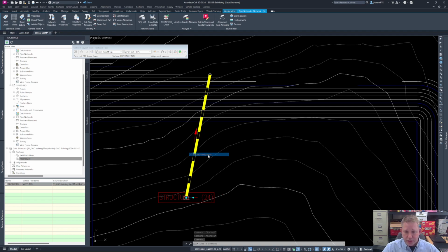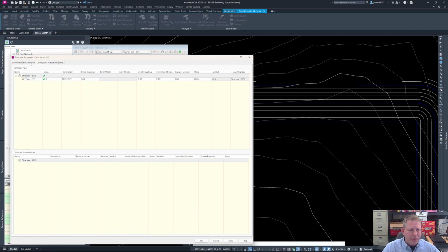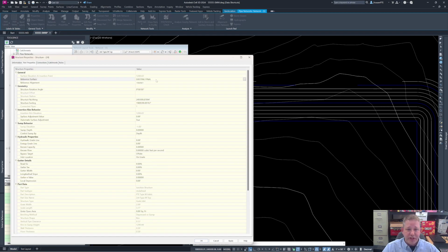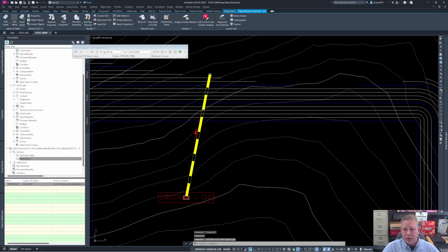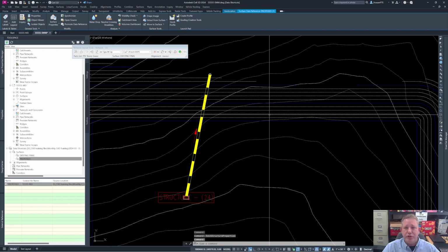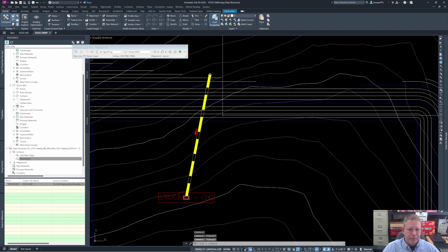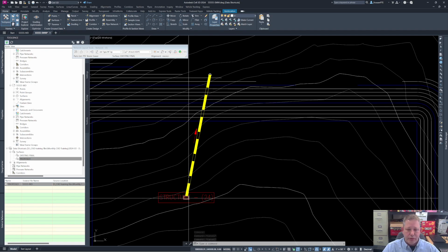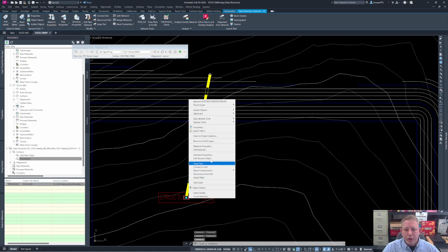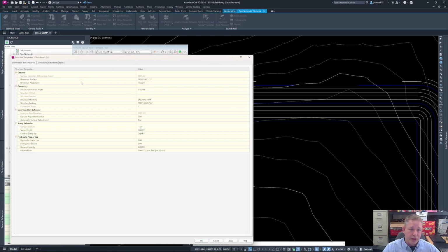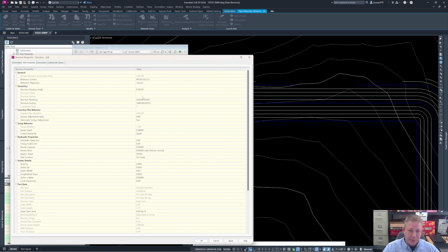We can now change the structure properties. Currently it was looking at the existing final. So if we change that to now go to our proposed, I guess this one. Oops. Okay. Actually, I think we got an extra proposed surface in there because of the crash. So now we have a proposed. We have that going to our structure properties, goes to the existing, or no, I'm sorry, goes to the proposed. So our top rim is 1295.